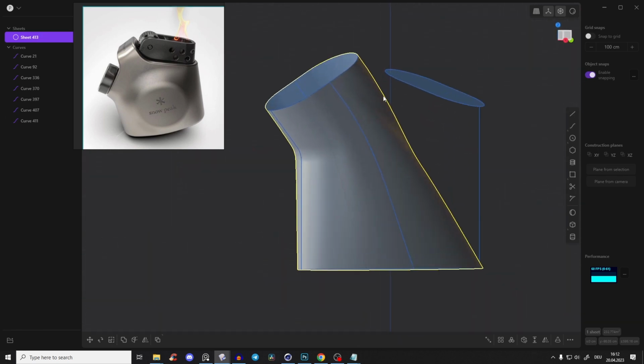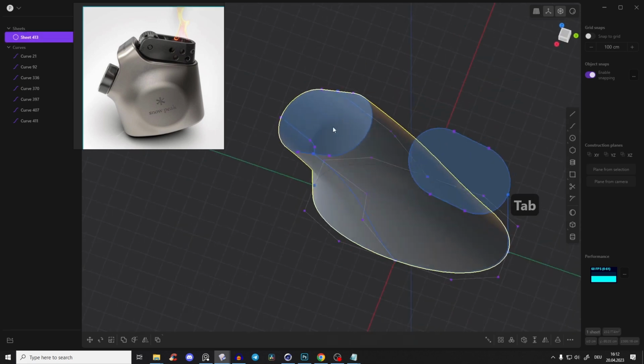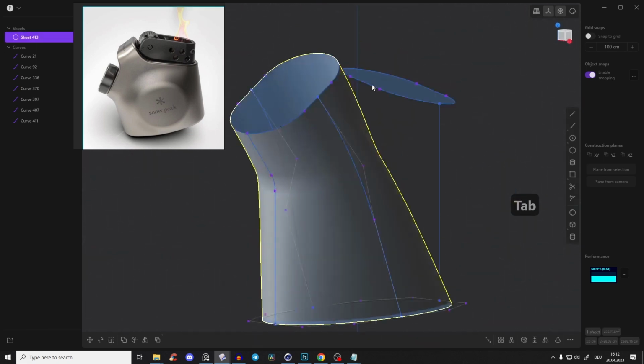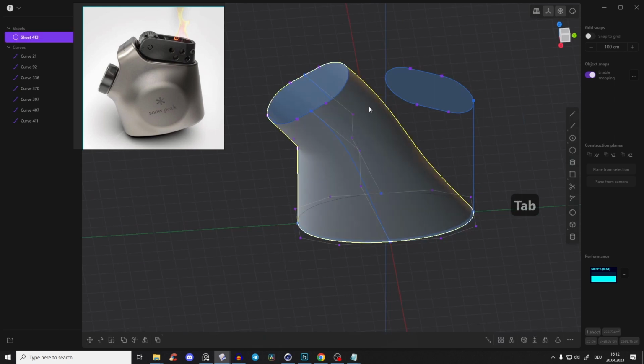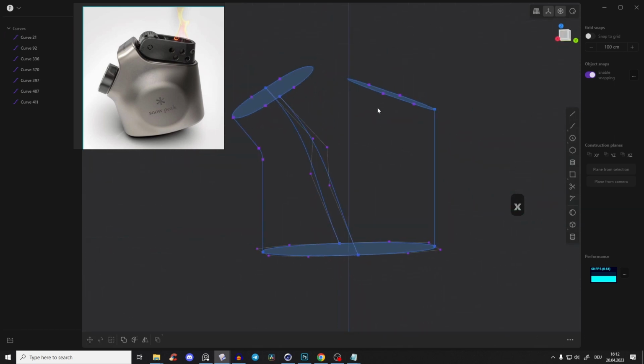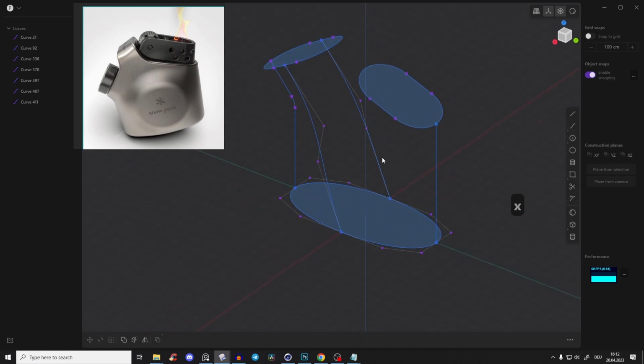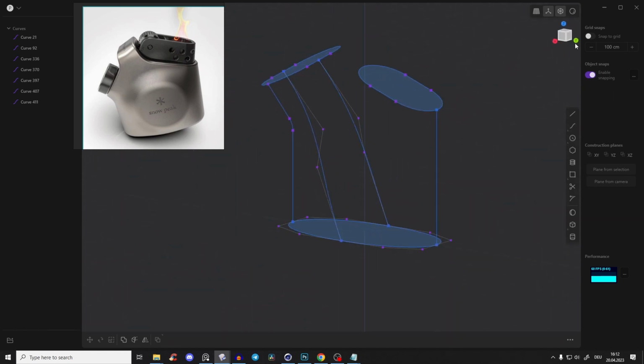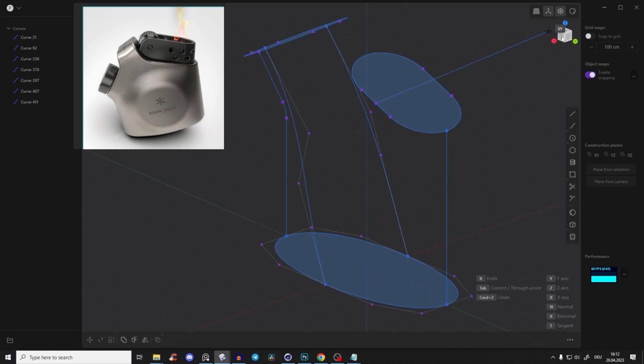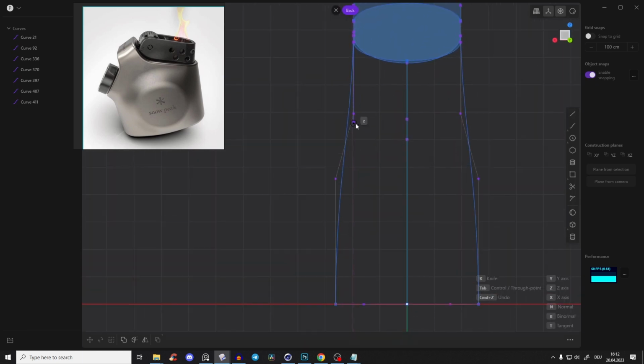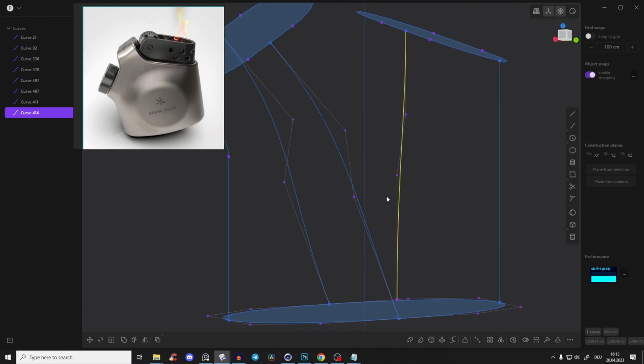And again, I won't do it absolutely perfect. I just want to show you some techniques because it's very interesting how we will do it. So for now, I will just delete it because we have to first do the same for the other side. So again, I create a control point curve to the middle and I go here to the back view. And again, I will just drag it down a little bit. And now again, I want to snap it here to the curve. So press Shift, you have a construction line and we can make basically the same curvature, right click.